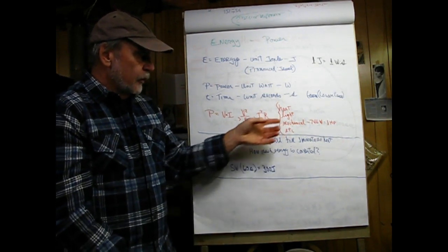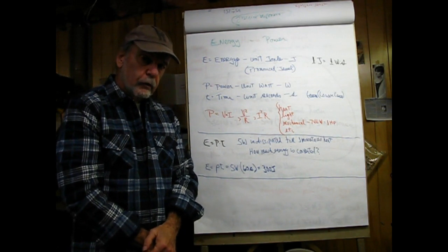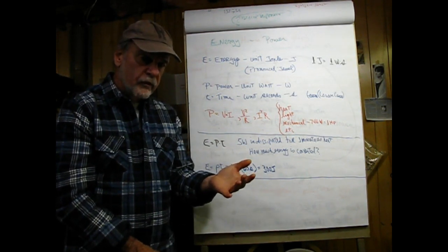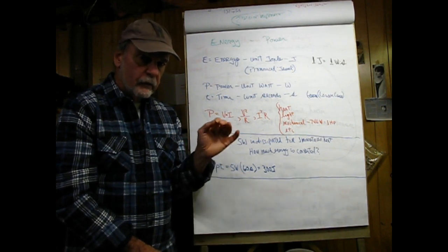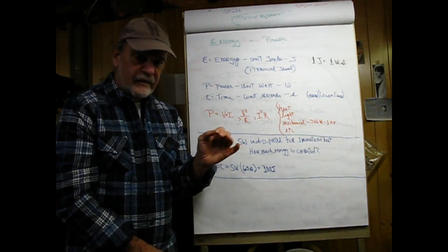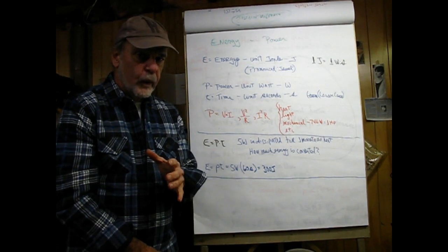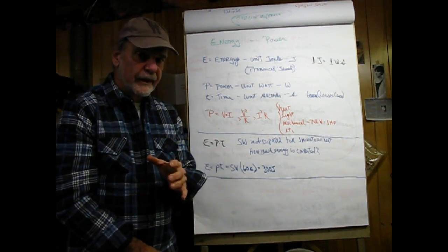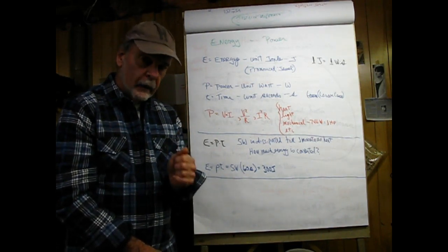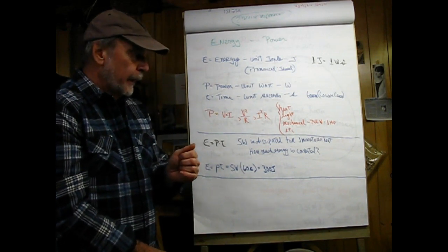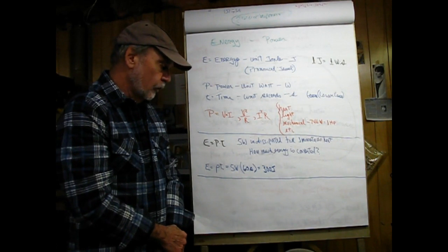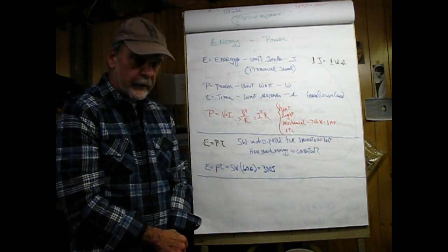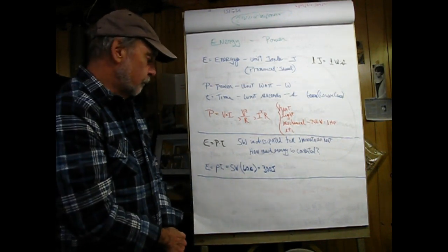And let me just mention, in the case of an incandescent light, for example, say 100 watts, you pay for 100 watts, and about 5 of those watts are actually converted to light, and 95 watts are heat. And that's why you probably, with your bare hand, cannot unscrew a 100-watt light bulb that's been on for a while. That has to do with the inefficiencies, if you will, of an incandescent light versus say a light emitting diode or a CFL.